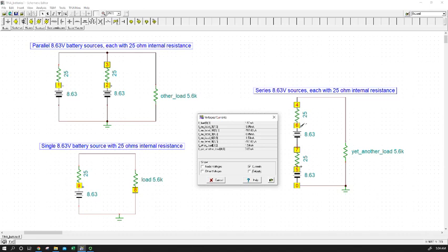So if we were to calculate the voltage drop over that resistor, of course it's going to be lower due to the lower current. If we were to calculate the voltage up at this node, at this corner that I'm circling, it would still be fairly close to our theoretical of 17 some odd volts. We wouldn't be seeing a tremendous reduction. In fact, we can calculate just using our TINA. We can back that node voltage out without opening up node voltages.